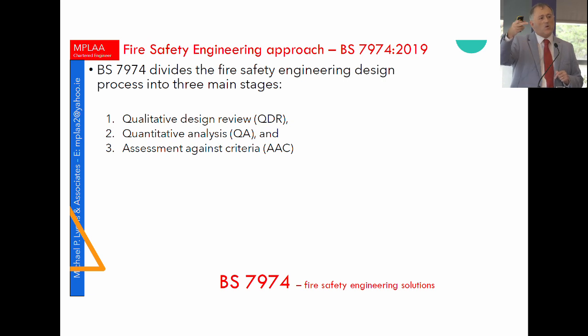And you've got to keep going back with the outcomes of every single individual fire scenario to prove that the response to the fire scenario doesn't breach those tenability limits. All of that gets packaged into a fire safety report and fire safety drawings, and gets submitted in exactly the same way for a fire safety certificate, but now the fire officer is assessing and they've got to agree with whatever your acceptability criteria are as well.